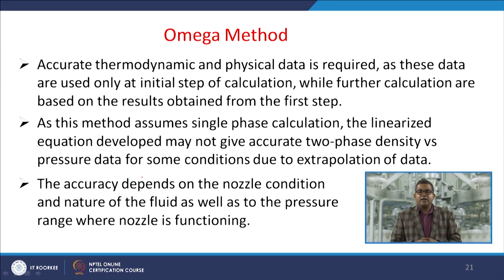One is that care should be taken while calculating data, as the equations developed are based on the analytical evaluation of the mass flux integral using an approximate linearized two-phase equation of state for the fluid density. Another is that accurate thermodynamic and physical data is required, as these data are used only at the initial step of calculation, while further calculations are based on the result obtained from the first step, which we have discussed in the